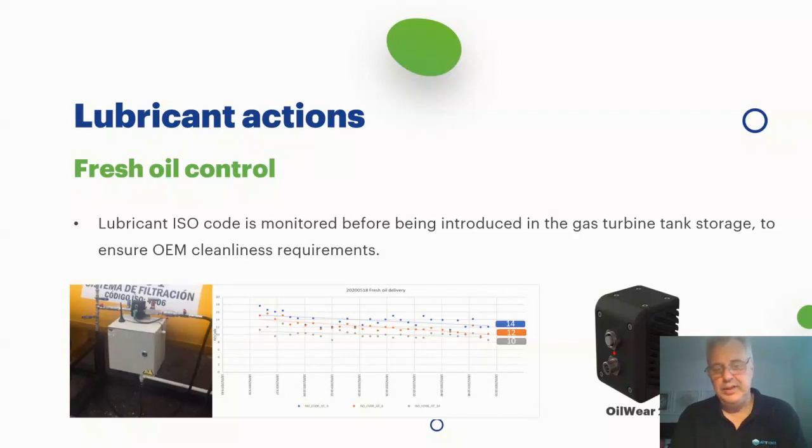Now we get to the point that lubricant dispensing at the asset is most important, obviously. In this case, for example, hydraulic and turbine oils normally require strict cleanliness levels. Online monitoring can be used to ensure specs are in accordance with the OEM. And of course, let's not forget the main reasons we talked about in the beginning.